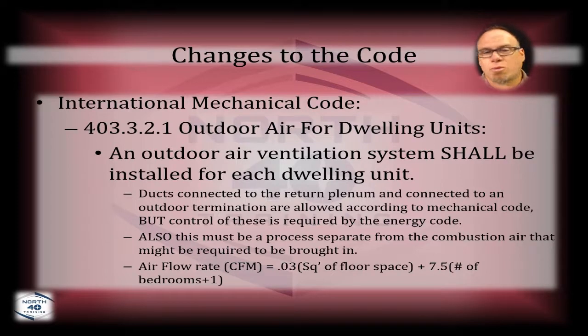Now we're recommending people run their fan 24/7 oftentimes, and there's some equipment out there where the fan goes down to just a fraction of its normal operating speed and it never shuts off in the off cycle, ever. If that's the case, now we'd be drawing in air all the time, even during the off cycle, so it would just be dumping unconditioned air into the space that would then eventually have to be heated, cooled, dehumidified, humidified, all those things. Not to mention you're bringing in contaminants from outside. So it's not as good a deal now as what it used to be.